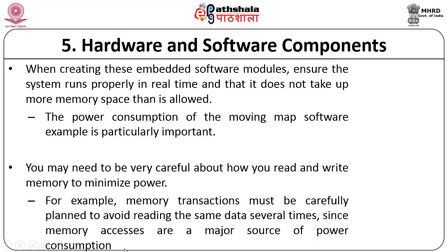When creating these embedded software models, ensure the system runs properly in real time and that it does not take up more memory space than is allowed. The power consumption of the moving map software example is particularly important. See, when I am looking at the GPS navigation system in real time, if I am standing in one position and I ask for a destination, it takes the current latitude, looks up the destination latitude, queries the spatial database, and extracts the route.